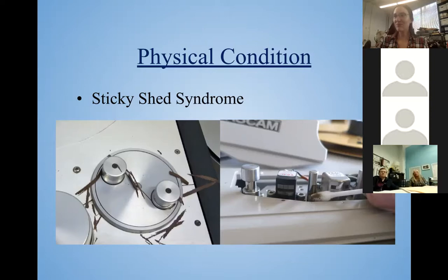So basically, you can see here, I have never seen audio sticky shed syndrome like that. That is the name for what happens when the water binds and creates the stickiness: sticky shed syndrome. People also call it binder hydrolysis. If you hear any of those, most people call it sticky shed. I've never seen anything that bad, where it's literally magnetic particles flaking off the tape.